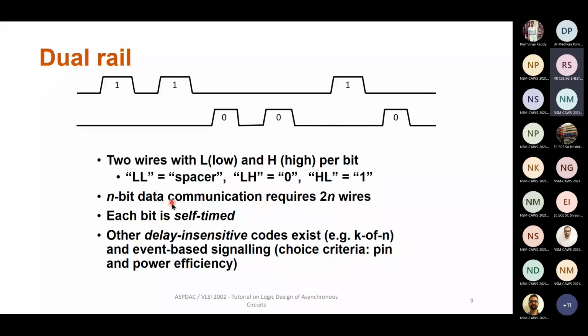So the expectation from asynchronous design was that if I'm adding small numbers, or any such unit which has a large delay variation based on the data input, then such systems will benefit more from asynchronous design than synchronous design, because asynchronous design would give average case performance, which is data dependent.